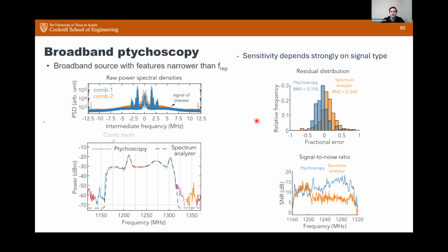So for this measurement that we were doing here, part of the challenge is that tunable spectrometers have difficulties measuring spectra that are not purely governed by white noise. For example, if you have a frequency which is rapidly sweeping around and you try to measure this with a tuned local oscillator, your signal is going to be very bad most of the time, because if your signal is moving around randomly and you're scanning linearly across that, you'll get very random fluctuations between each successive scan. And so your SNR is usually going to be quite poor in that case. In this case, Terahertz does quite a bit better. For purely incoherent spectra, it's usually not going to be as good, though.